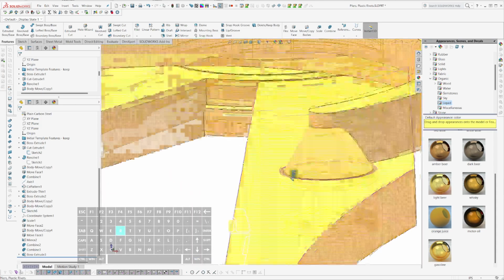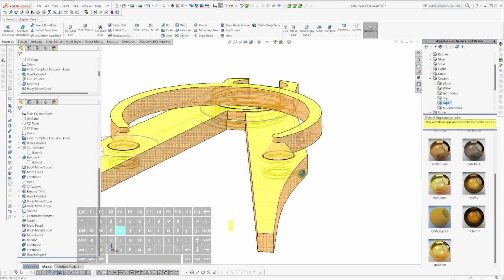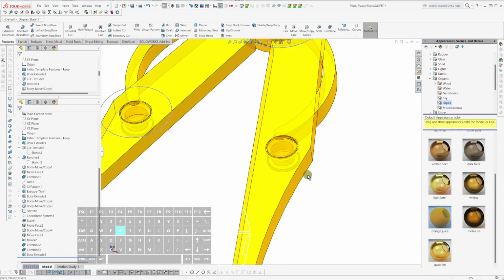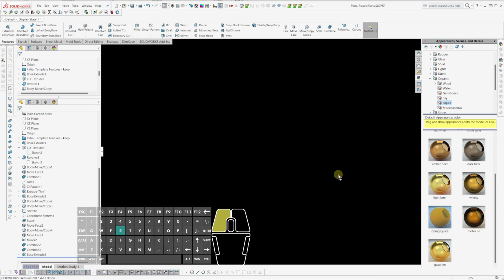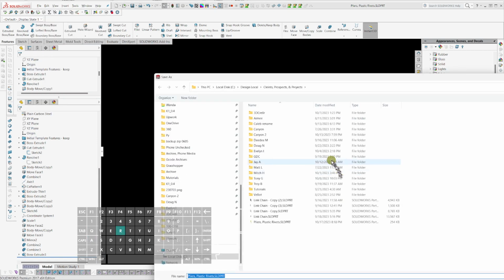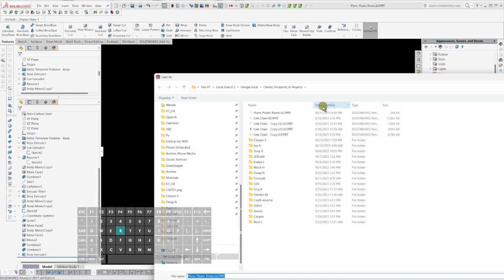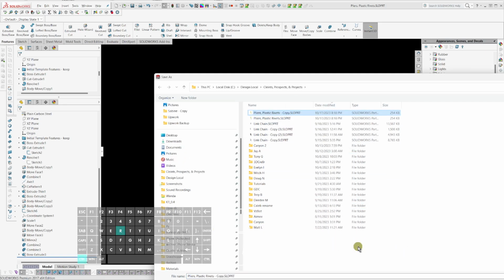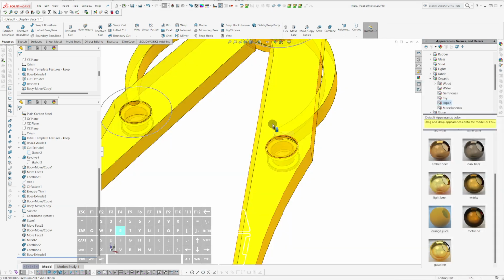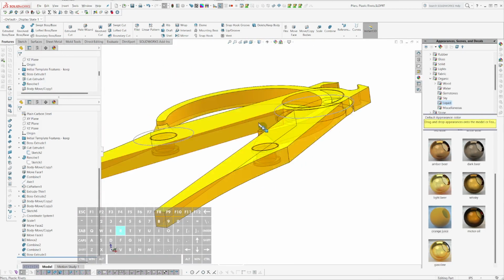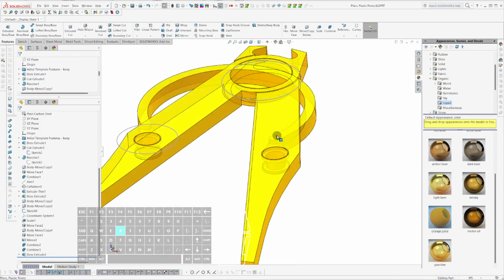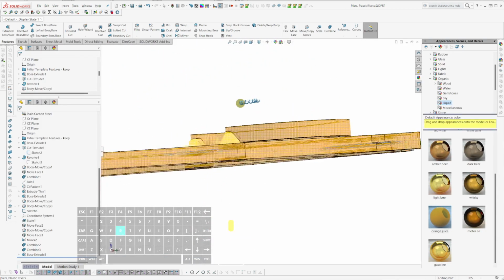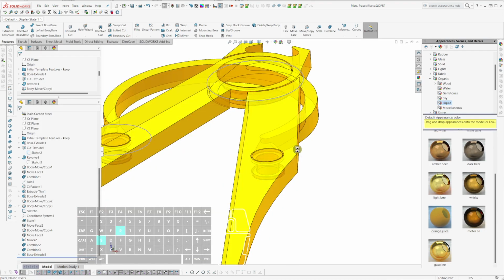so we're looking good, except I need to reinforce this area a little bit. So I'm going to save. I'm going to do my backup routine. Alt F8 and sort by date and drag and drop while holding the control key gives me a backup copy, as you can see. It's an excellent tip from an old man that's been around the block a million times. All right, so now let's save once more for good measure.